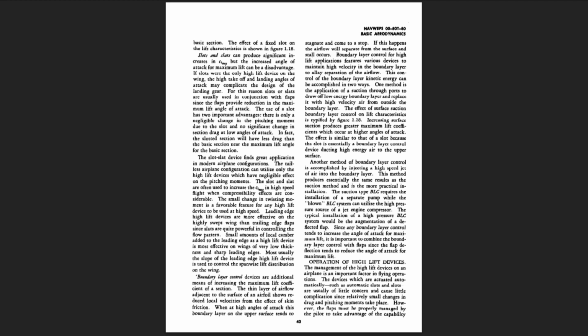The use of a slot has two important advantages. There is only a negligible change in the pitching moment due to the slot and no significant change in section drag at low angles of attack. In fact, the slotted section will have less drag than the basic section near the maximum lift angle for the basic section.